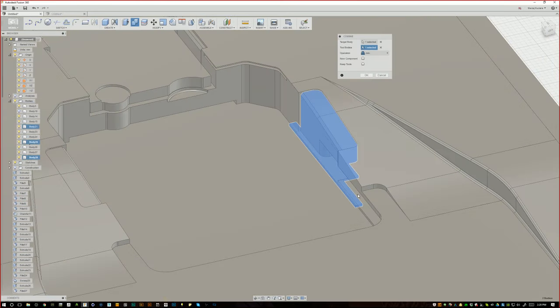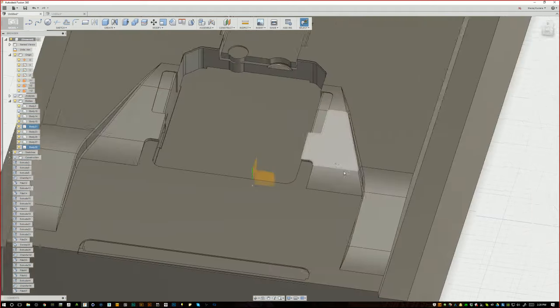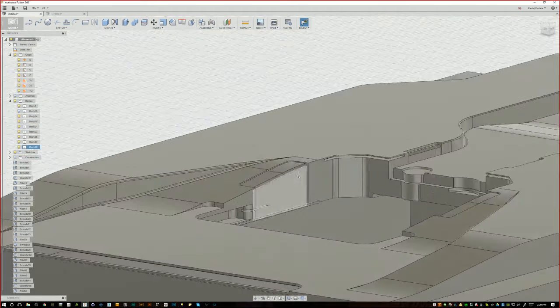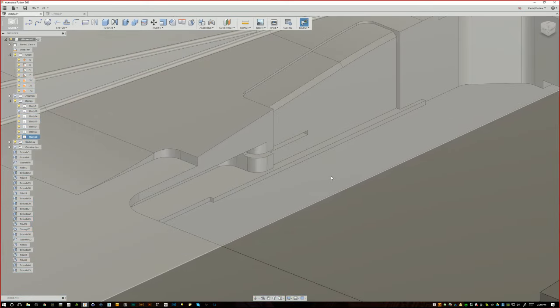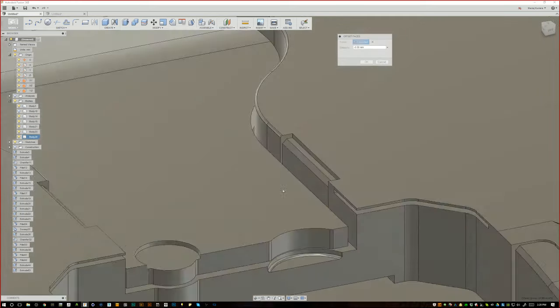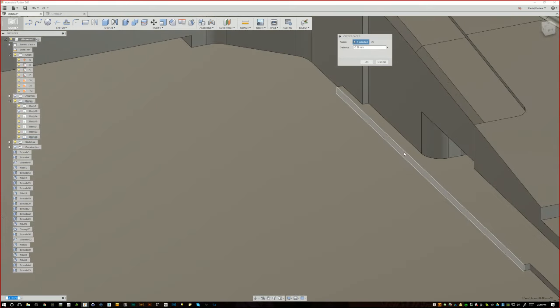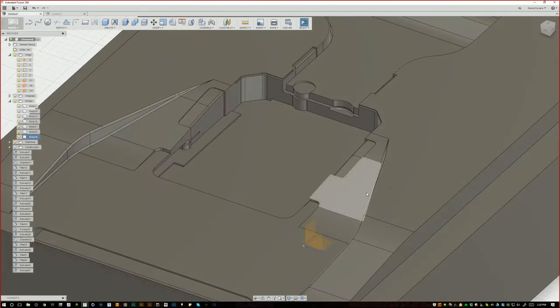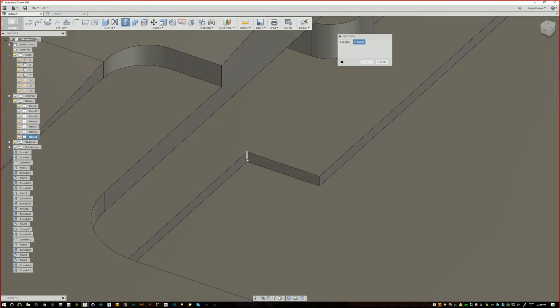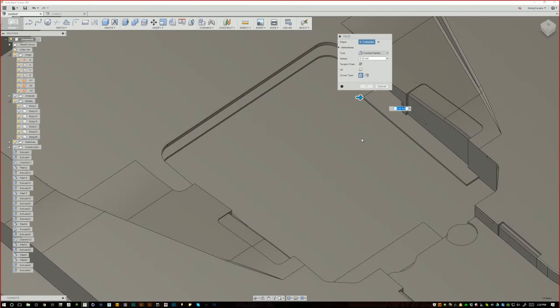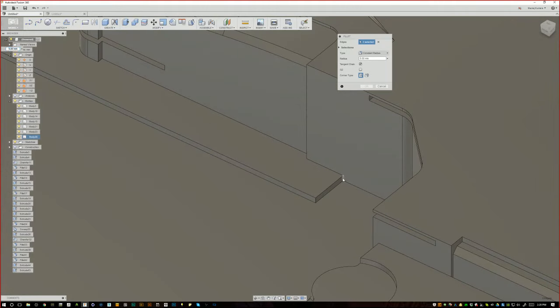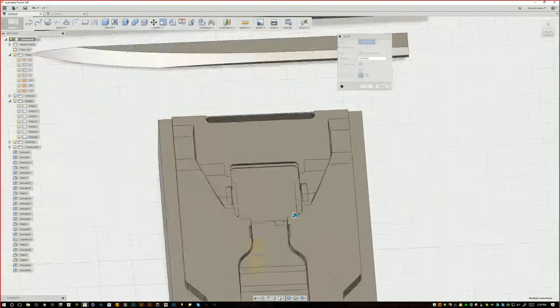Awesome. Next question says, the flow is like making props or an entire scene and exporting to Maya or 3ds Max to make the composition and camera. So the way I work with this is I do the hard surface modeling here, which is basically what I'm doing right now on the stream. And then as soon as I'm finished, I export this file as IGS, because that's the best format I found to export from here, and then go directly into Max, import it there, and build lighting and everything in Max.